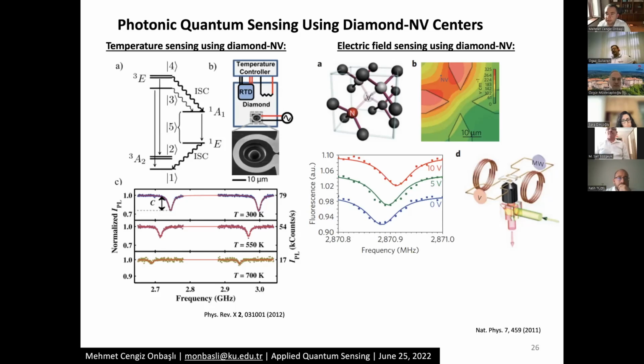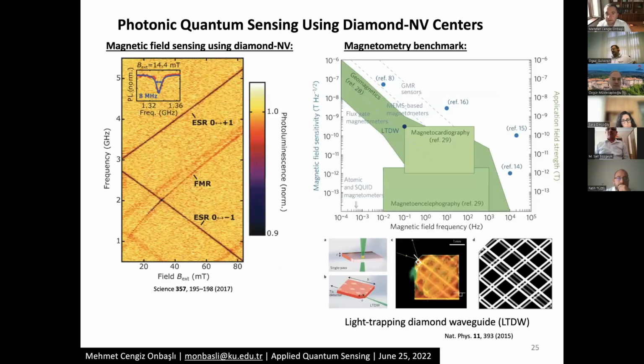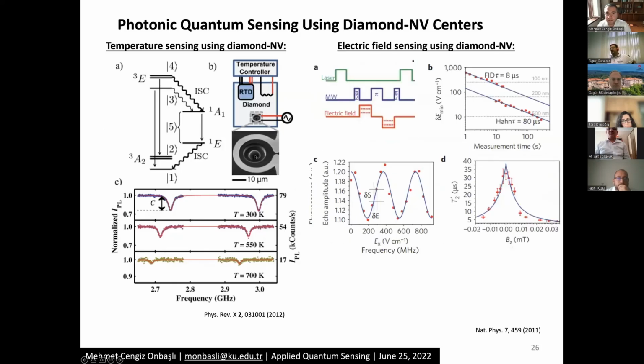People have been using confocal fluorescent or confocal photoluminescent microscopy with a piezoelectric stage that controls the position of our readout to pick up individual isolated NV centers from the chip. We excite the whole chip, but only pick up fluorescence from that individual NV center. This allows us to read individual NV centers' T2 signals.